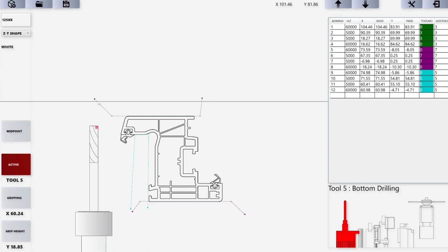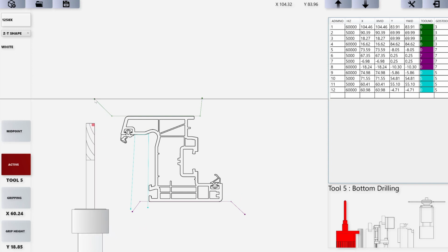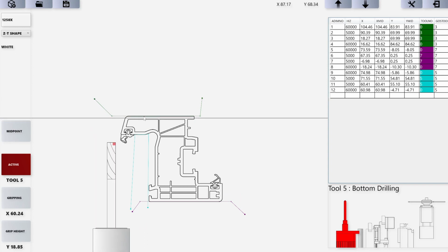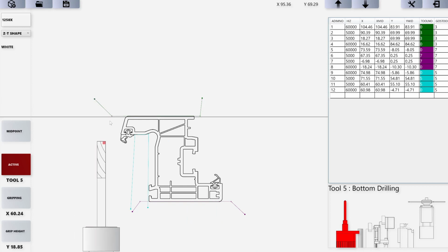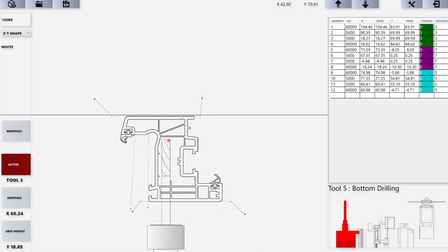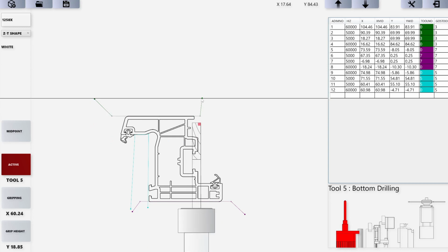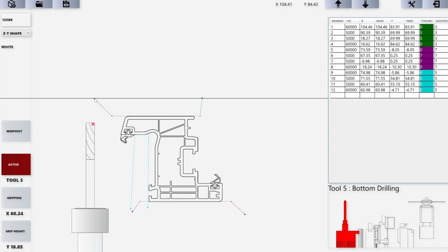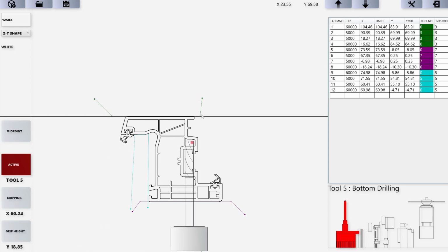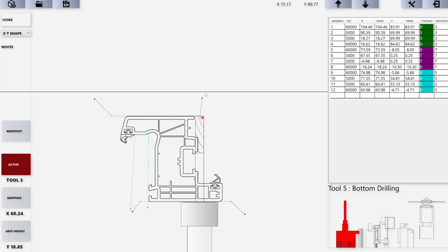So all of my steps are fast, slow, slow, fast, which is idle move, operation move, idle move again. So we go to the position fast from the safe distance, activate the tool, finish the cleaning, and escape back to a safe distance again.